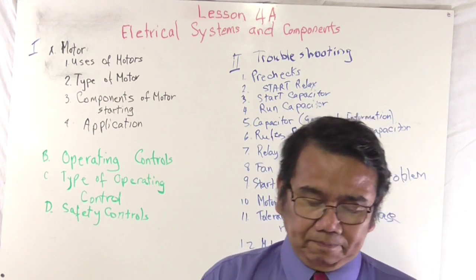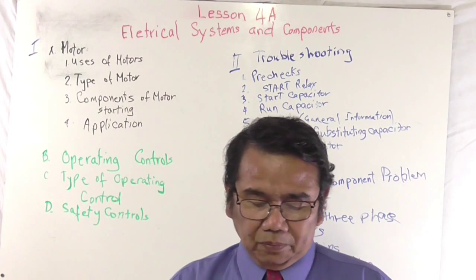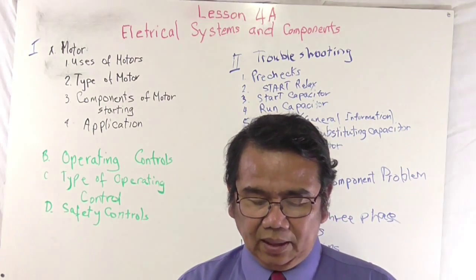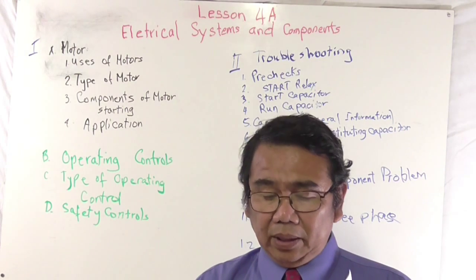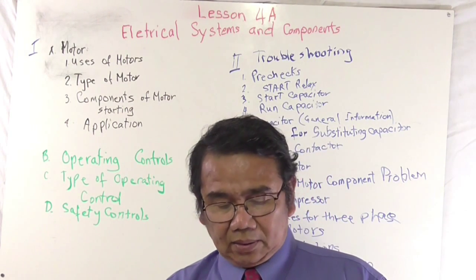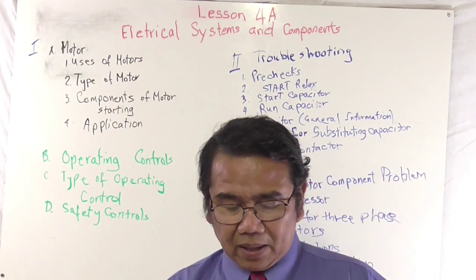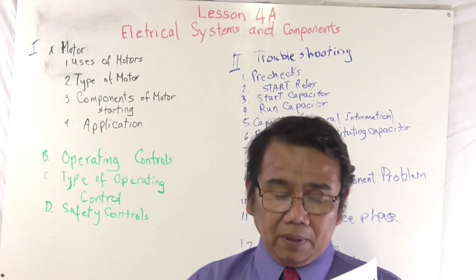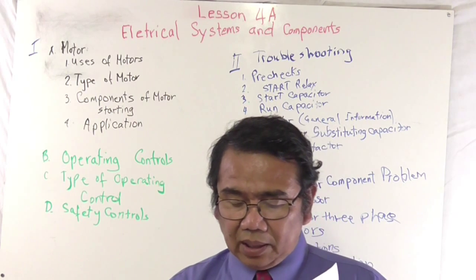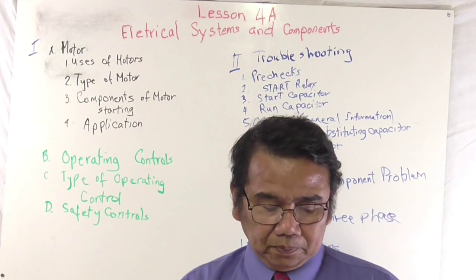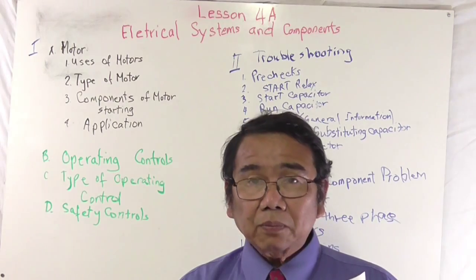Rapid opening and closing of the relay contacts, okay, eventually burning out the contacts and eventually burning out the start capacitor. Never replace a potential start relay with one of a different rating. Very important.